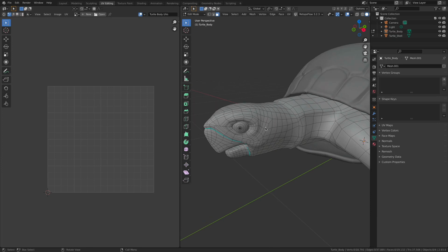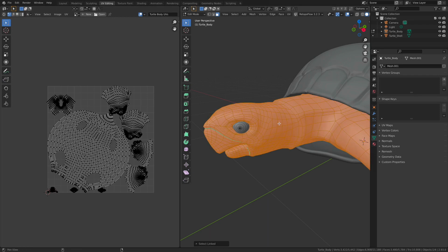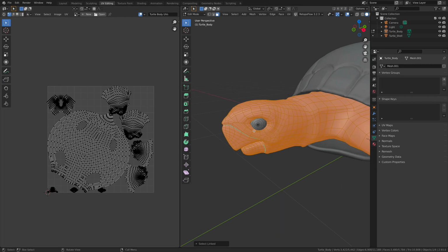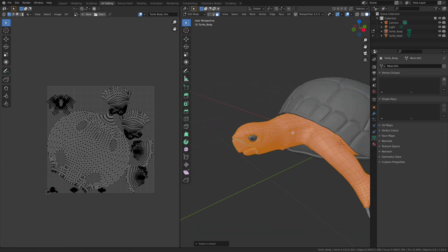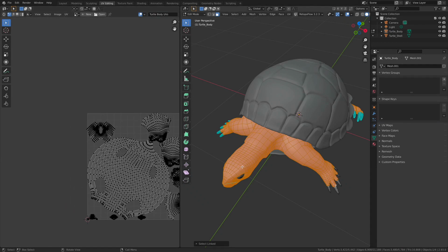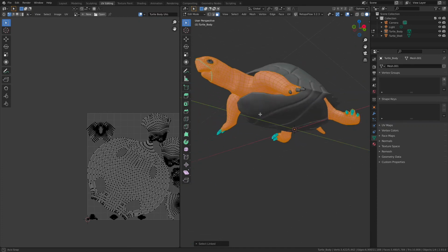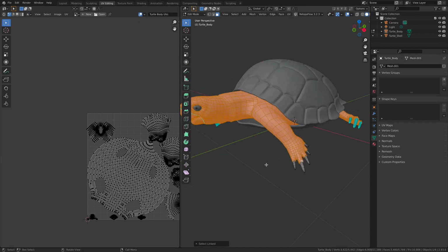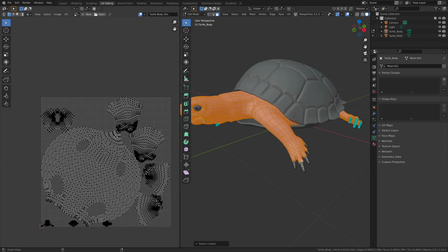However, I've already UV mapped it, and this is just kind of a habit that I've gotten into. Whenever I retopologize, I just UV map real fast. That way I have them. The UV mapping tools inside of Maya are really good, and I want to make sure that I can access all of those UVs, and more importantly, the seams, in case I make a real big structural change to the model itself. If I really want to make a big change, well, I'm allowed to do that, but I don't want to lose all those seams.